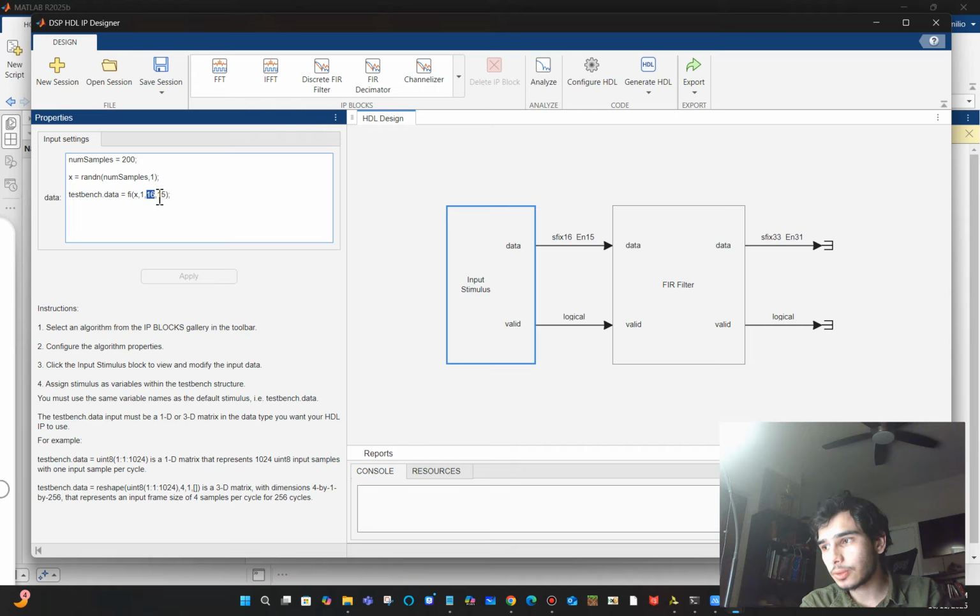Because our analog to digital converter was 12 bits, we're going to need a lot. So 24 bits total, 8 bits fraction, and these numbers are good because for 24 bits total, it means that when we use the ADC output, it's going to have a lot of leading zeros. So it's not going to overflow or anything. Because this filter